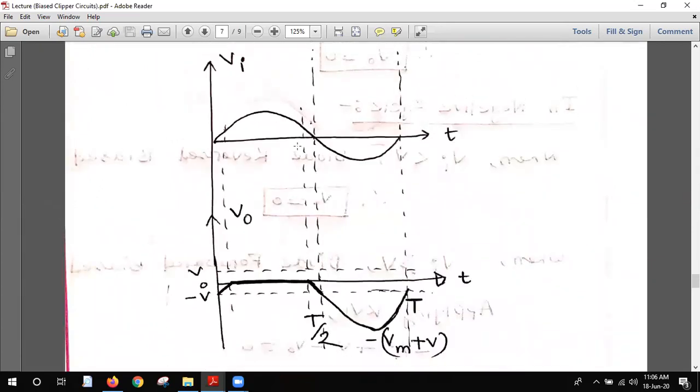Okay, my student. Whatever we have done in the calculation, now we go back to the final waveform. This is our positive cycle, so we'll first discuss the positive cycle. In the positive cycle, we told you that at some portion it is forward biased and in some portion it is reverse biased. In the forward bias, it is something like this. This is the forward biased position.